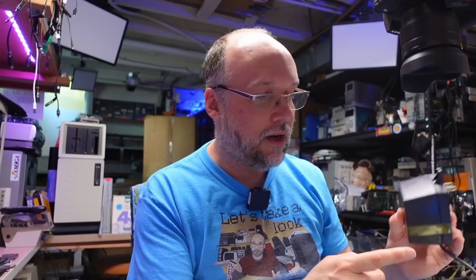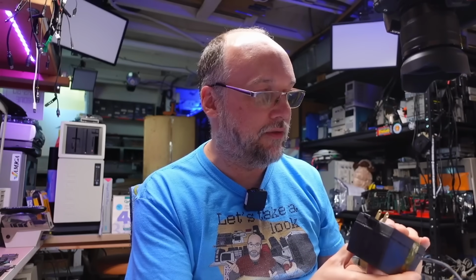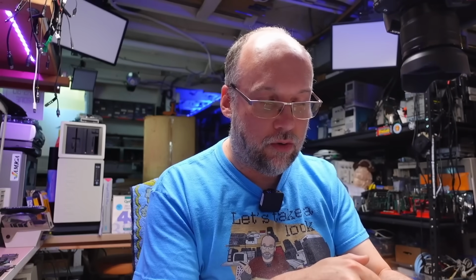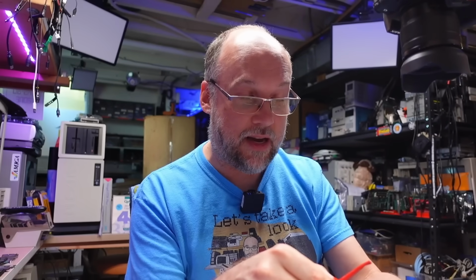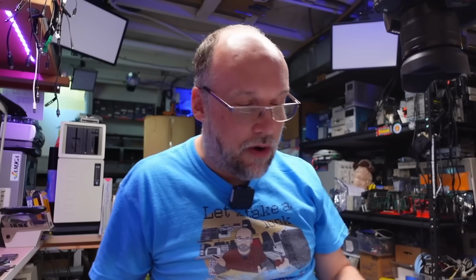Oh, you know what we should do? I should have done this before I taped this up. I should have measured the AC voltage coming off the different windings. I think what I should do, just for fun, is power this thing up again with the bench power supply going directly into this capacitor. So we're going to bypass the AC voltage going in, and let's see if the modem clicks at that point.